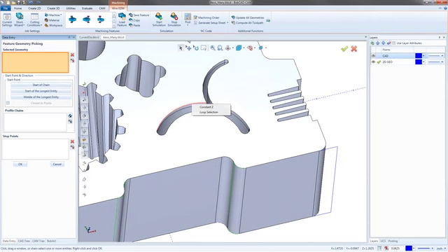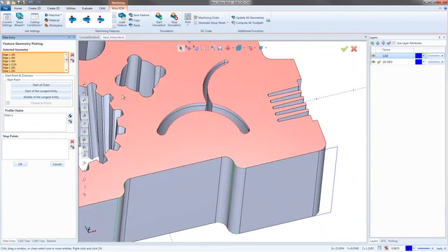And then right-click on it, and you'll get 2 options, Constant Z and Loop Selection. In this case, because the entire shape I'm thinking is on the same Z level, I'm going to say Constant Z. And if everything works, I'd like to see it. There it goes. Grab the entire chain around the top of that. And because it's all on the same Z level, it should grab the entire chain. So from here, I can go in and say, right here, we can set up a start point. So we can actually go in and we can say start at the start of the chain, start at the longest entity, or start in the middle of the longest entity.